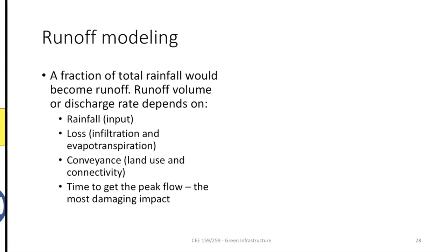That depends on the impervious surface as well as the slope and other factors, or the friction that the land will exert on that flow of water. That's why if you have a grassy area, it soaks up a lot of water before it flows. But if that same raindrop goes to your parking lot, it becomes runoff quickly because there is less friction to store it.